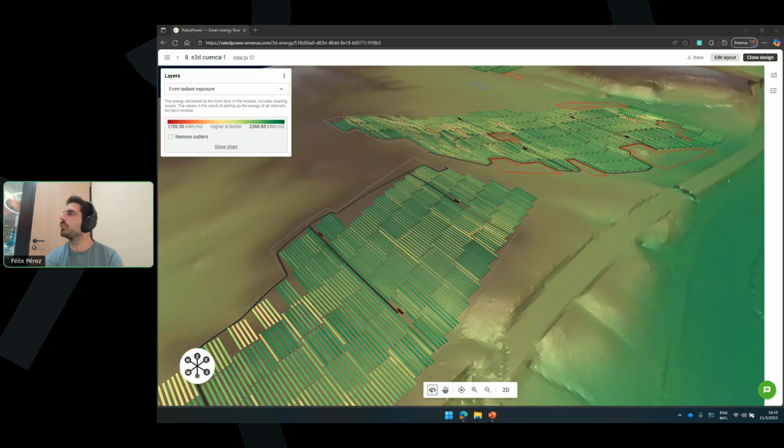Are you able to modify the terrain to show areas that have been cut and filled to reduce the slope? Yes, earthworks. You can either upload terrain which has been modified in a custom terrain, or you can use the earthworks feature in RatedPower, and that is taken into account for the energy simulation. However, our earthworks feature produces flat platforms, which are very large and cast shadows on their own, so it's not super optimal. But you can consider the modification of terrain.